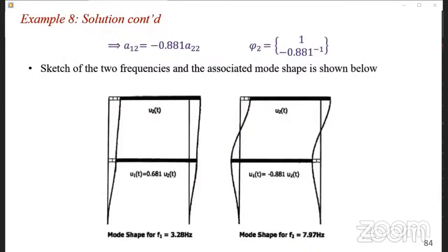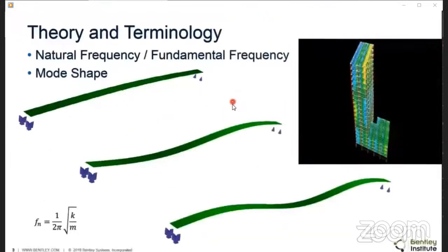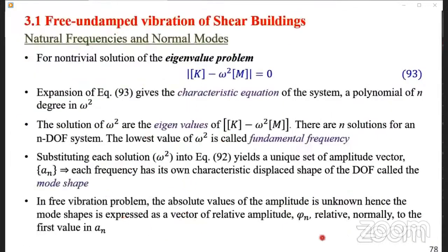And a number of ways of normalizing was setting the maximum value to 1. And that's why in this case here, we were setting the deformation value for the second part to be 1, so that you are expressing this as a ratio, to normalize the mode shape. And this was again explained in this part. So this paragraph number 78, this slide is highly summarized, and that was being explained in that small video about how to obtain the mode shape when you solve the eigenvalue problem.